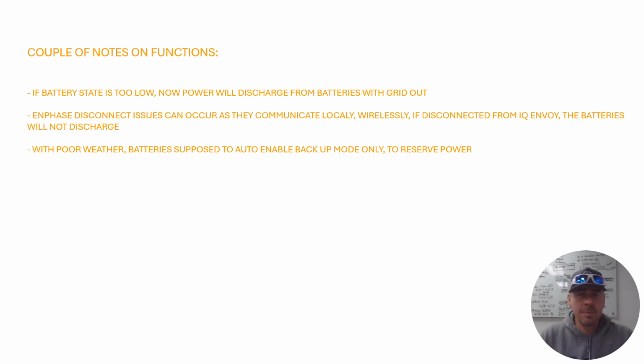If there's any lapse in communication, where a wired or wireless connection is not happening, and the controller, the brains, the computer for the system, cannot talk to the batteries, then it goes into a safe mode and standby, and they just won't discharge. So if you see any errors for connectivity, they're not working, unfortunately. If it's not talking to the computer, for safety purposes it has to go into standby. And so there are some caveats.